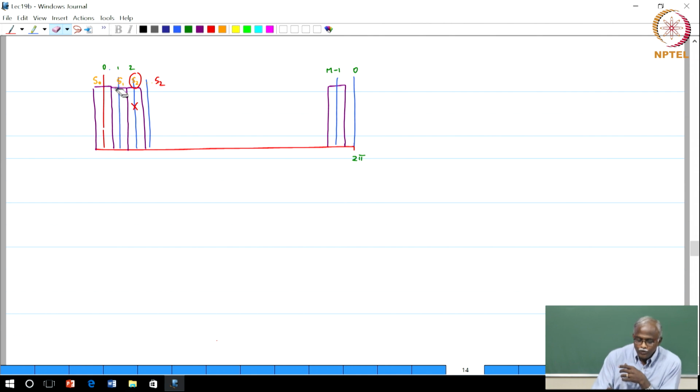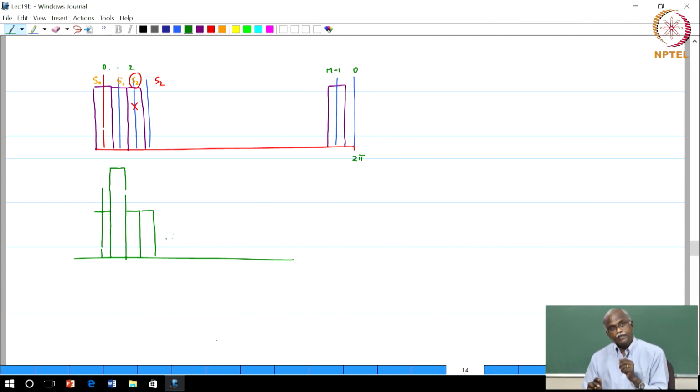What you would do is boost the power of this particular signal, right. You would transmit more power on S1. So, the spectrum would now look like this is S0, and S1 alone you are transmitting with a lot of power, and all of the others at normal power, let us say. Okay. Now, how do you achieve this?